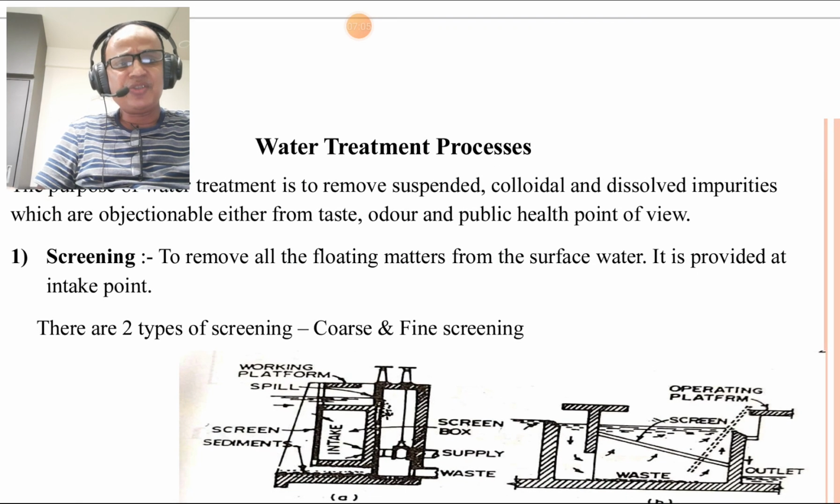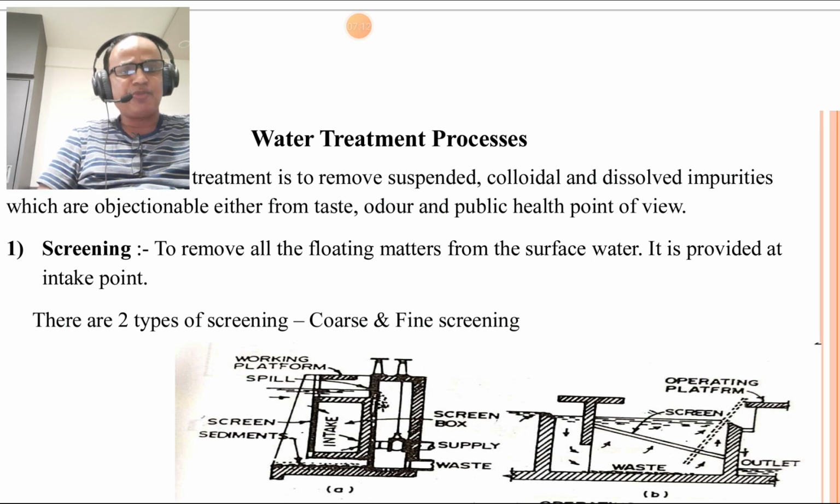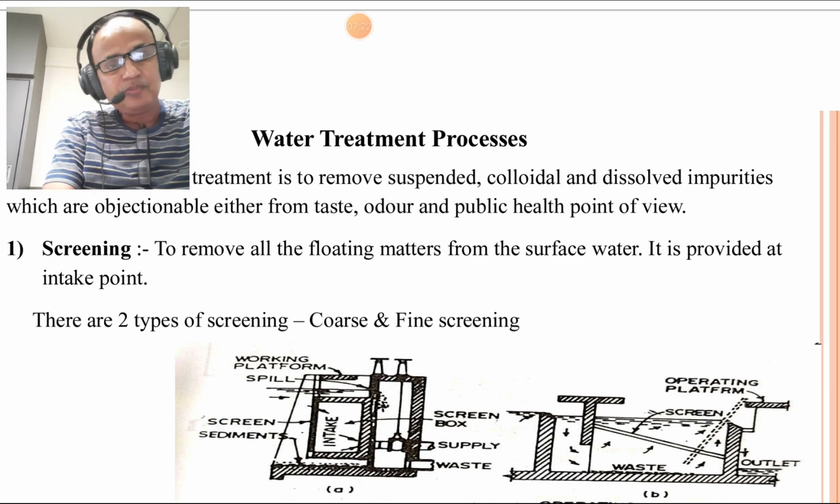First of all, we discuss the screening. Screening is to remove all floating matter or materials from the surface water. It is provided at the intake point. There are two types of screening. First is the coarse screening and second is the fine screening.